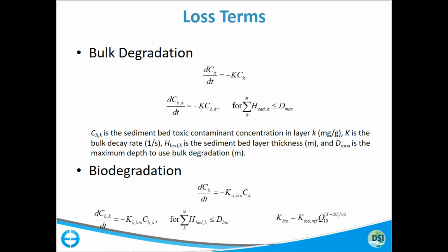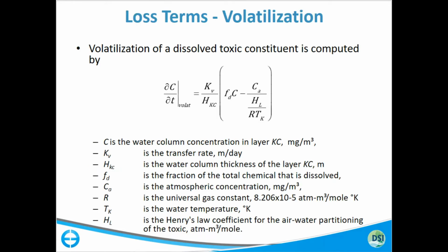If temperature is not even being simulated at all, but you need it for toxics work, we'll talk about this with the user interface, temperature can be externally specified just like the DOC values that we were talking about. So you don't actually have to simulate temperature to have its effect included in the model. And I'll show you that when we get to the user interface.